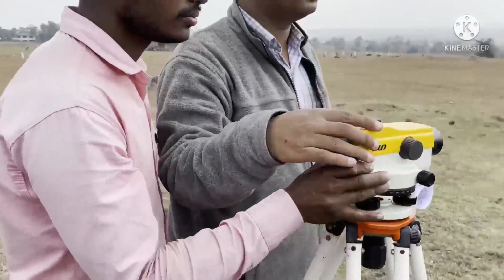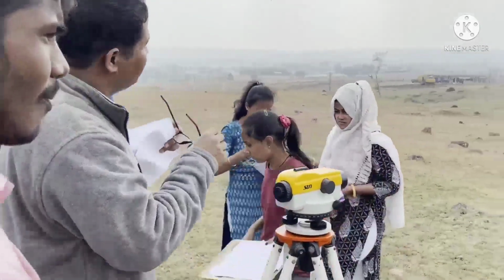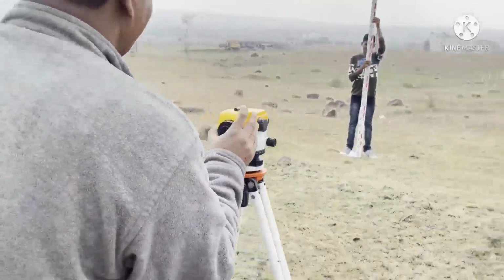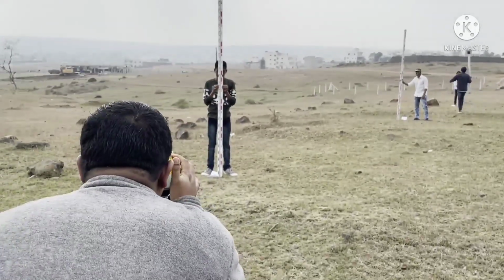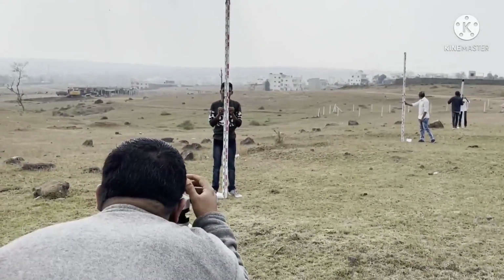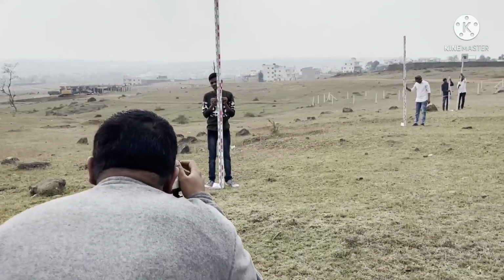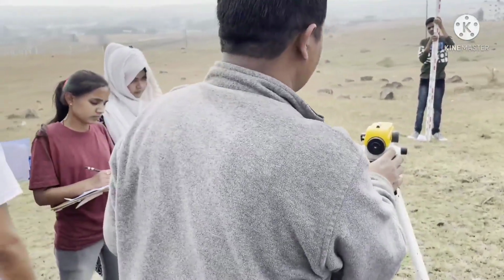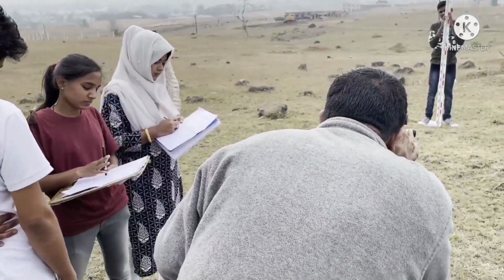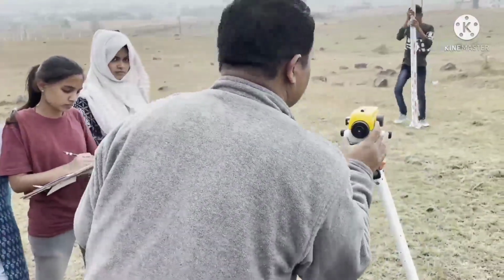Now the persons carrying the leveling staff will be shifted to the right hand side for taking the staff readings of the first line only, of the chain edge 0, on the right hand side. So this is the person standing on the C0 R10. It has been bisected using the auto level and correspondingly entered. After completing that staff reading the person will move.